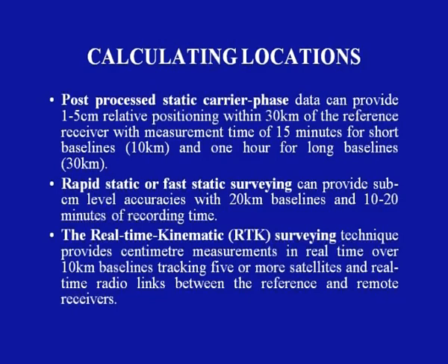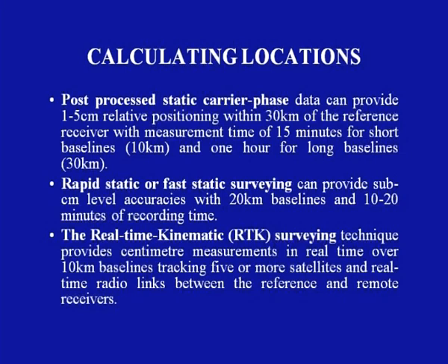Rapid static or fast static surveying can provide sub-centimeter level accuracies with 20 kilometer baselines and 10 to 20 minutes of recording time. In real time kinematic surveying mode, which we call in short the RTK technique, it provides centimeter measurements in real time over 10 kilometer baselines, tracking 5 or more satellites, with real time radio links between the reference and the remote receivers.